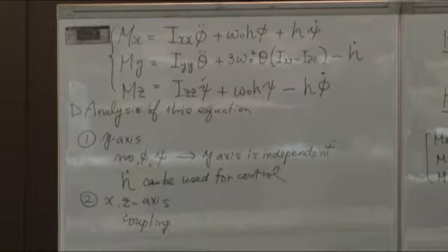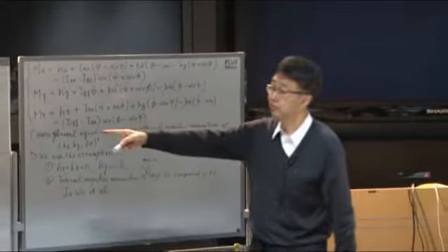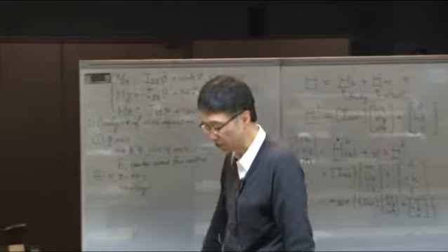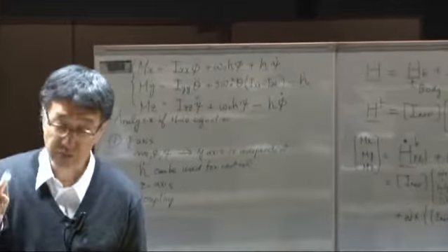But omega 0 is very small as compared with the spinning satellite. In the spinning satellite case, the x and z-axis coupling is made by the spinning speed of the y-axis. But in this case, only the x and z-axis are coupled with the term of omega 0.